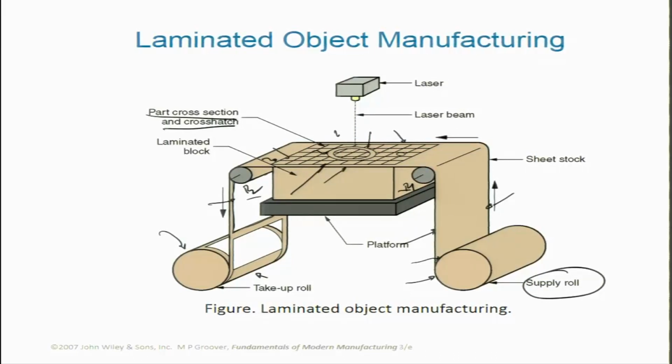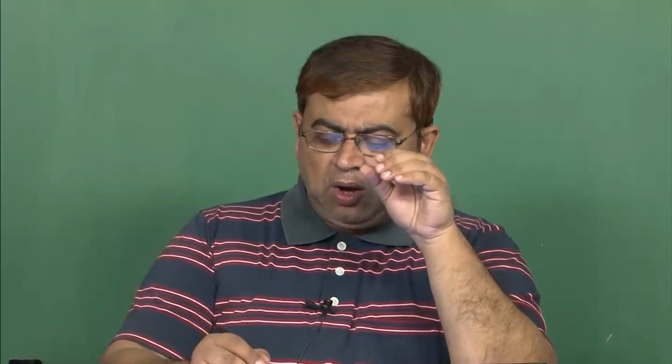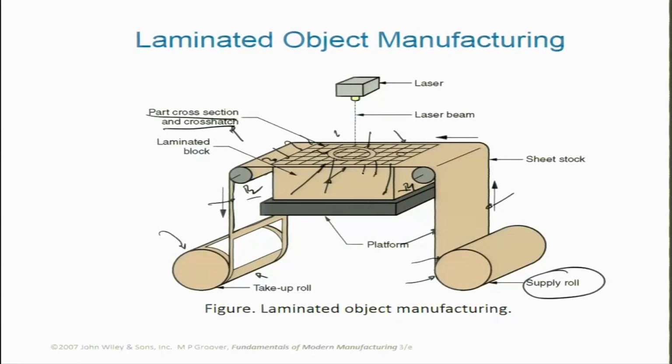The idea is that later on the cross hatching is typically done because we want to remove these portions easily, so that the part which is actually not cross hatched remains back. This cross hatching probably is at a level or a dimension where a slight amount of effort releases these very easily, because they are smaller in size in comparison to the overall part size. And so the idea here is that these all are blocks which are being formulated with the part, and these blocks are getting lost, while supporting the part as the part is getting built up three-dimensionally.